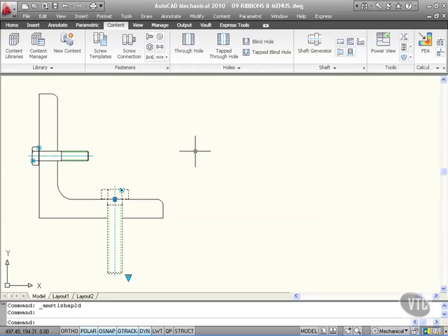If I delete this here, this is very clever. Notice when I delete that, it still leaves the gap. If I do a regen, will that help? Let's check. No, it doesn't. Because, obviously, it cut that hole originally to place that bolt through. So, there's no turning back sometimes. I'll just undo that and bring that back in again. So you've got to be careful there, because once you've cut through that, obviously it's gone.